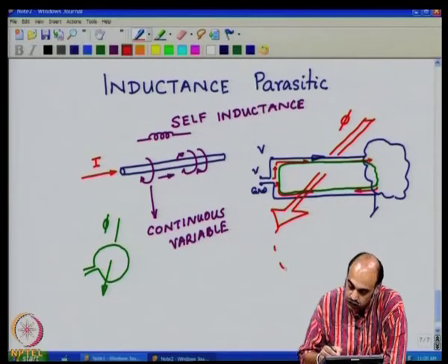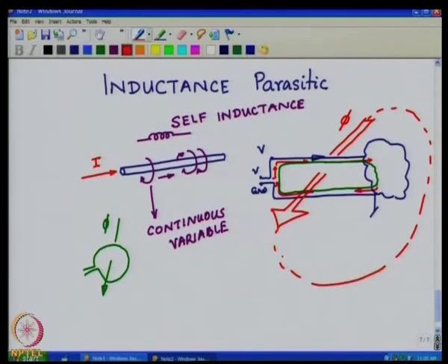It will then complete the loop through some other circuit or maybe even free air. Now, a flux going through this loop implies that the current in the loop cannot change instantaneously, which means an inductance is set up here. It is a parasitic, distributed here or here, but shown lumped. So, an inductance can be set up just by a current carrying conductor, self inductance.